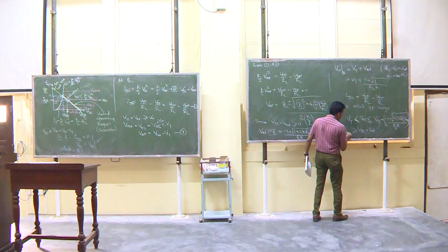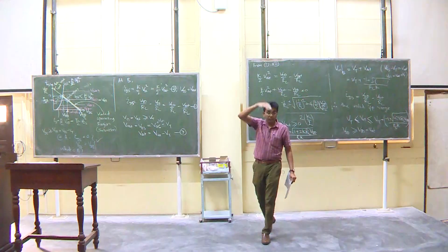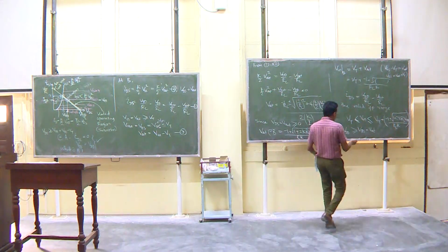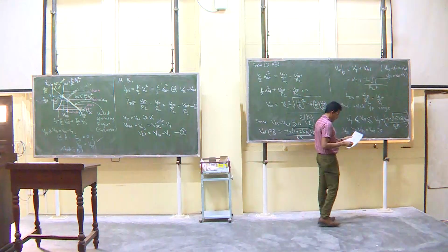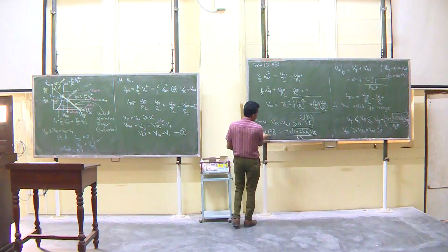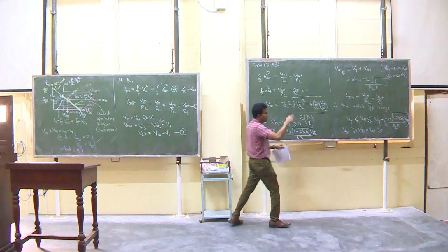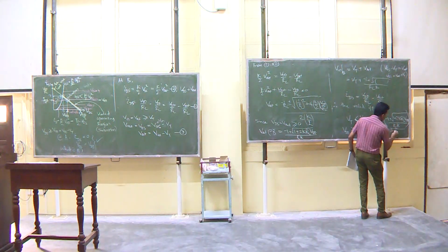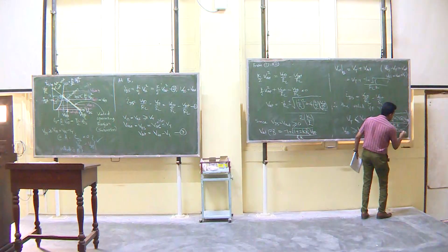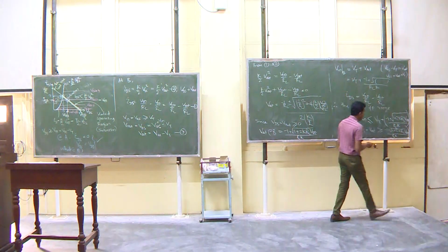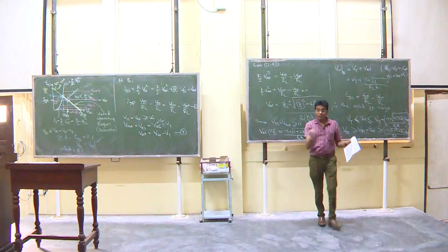It cannot be more than that. It can't go above the supply voltage. No? It has to be less than that, but it has to be greater than 0. V out has to be at this point. This is that, so up to that value. So minus 1 plus square root of 1 plus 2k RL VDD divided by RL K.